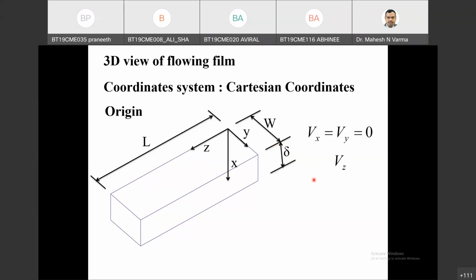Maybe if we have enclosed boundaries on all sides in the z direction, with only one side open, that is a closed flow condition. Then the continuity equation for liquids would be violated. Hence there will be negligible acceleration in the flow. This is the main reason why we are neglecting that Vz is a function of z. So Vz is constant in z direction. Everybody got this point?